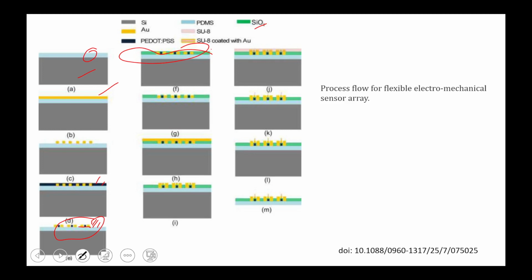So either you deposit SiO2 using silicon as a substrate and oxygen as a source material with an RF sputtering system, physical deposition, or you use an oxidation furnace. You deposit 30 to 40 nanometers of that oxidation layer as an insulator, and then you remove it above the gold pad using KOH solution or some solvent, and again deposit one gold layer here to make the contact.